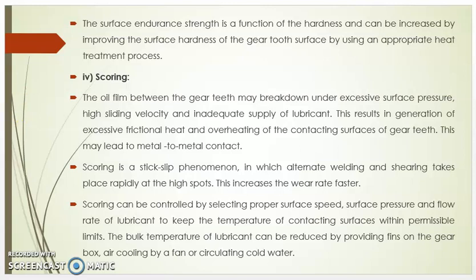The oil film between the gear teeth may break down under excessive surface pressure, high sliding velocity and inadequate supply of lubricant. This results in generation of excessive frictional heat and overheating of the contact surfaces of gear teeth. This may lead to metal contact. Scoring is a stick-slip phenomenon in which alternate welding and shearing takes place rapidly at the high spots. This increases the wear rate faster.